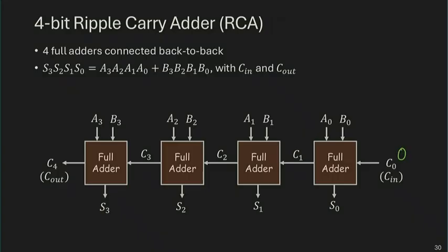All right. So let's try to plug in some of the binary numbers and see if it works. Anyone want to give me a 4-bit binary number? 1, 1, 0, 0. I'll use that as my number A. Right? Break it down into 4 bits based on its positional weights. Send it to the 4 separate full adders. Give me a second number.